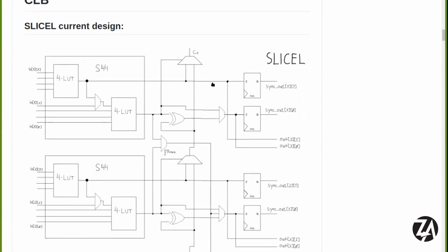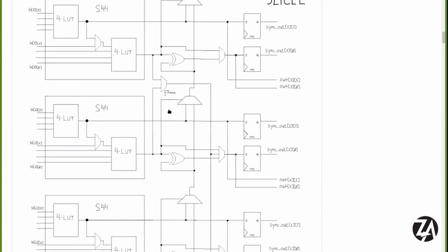Okay, so the way we organized the design was bottom up. We got one team to work on the configurable logic blocks, which has the LUTs in it. Another team to work on an SRAM tile, and another team to work on a multiply accumulate unit for faster arithmetic. And so I can just go through this from the bottom up.